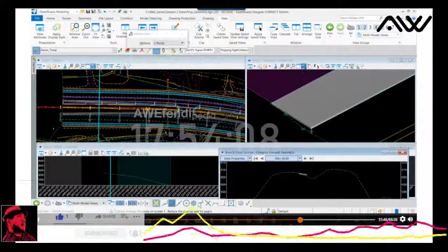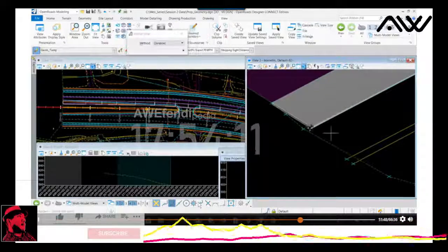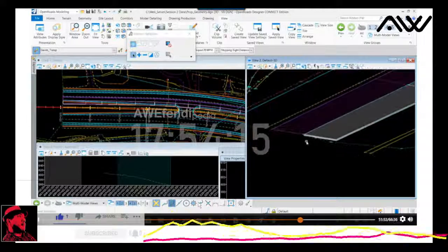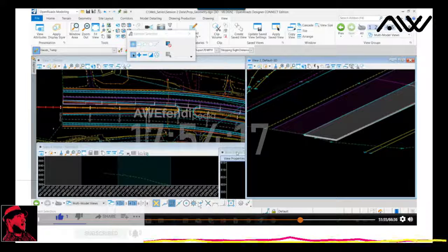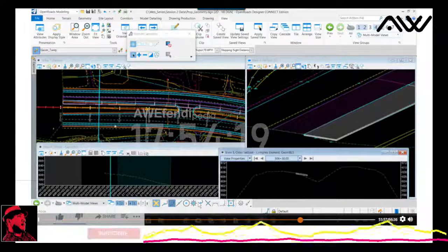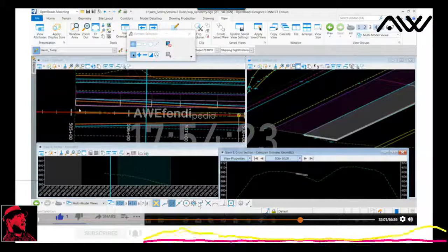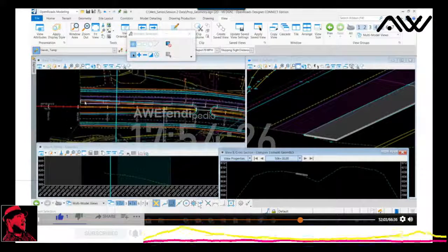Click the right active view. So we see that widened pavement section. And again, this is temporary. We're only doing this to locate where we want the PGL to be. Now, I'm not going to do this on the south side of the road again for time's sake. We would reproduce this exact same workflow on the opposite side of the bridge.